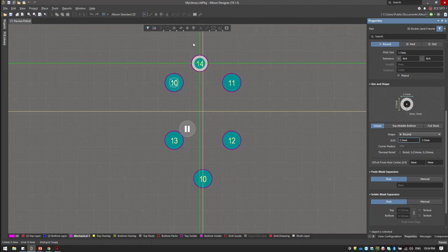So here 2.5, I would always go 1 millimeter cover on top of that for a mechanical support hole. As you can see, if you add more cover, let's say 4 millimeter by 4 millimeter, all that in here is cover, and this is the hole only. So just 1 millimeter of cover is more than sufficient for that.